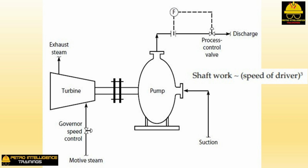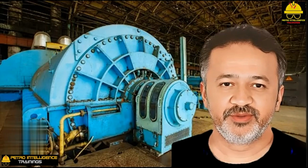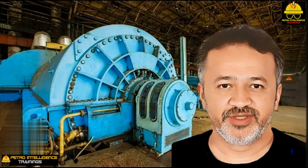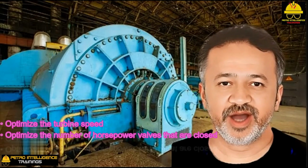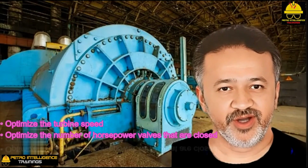Slowing a turbine closes the governor valve. This may now permit us to close an additional horsepower valve without losing our flexibility to control the speed of the turbine. Closing that final horsepower valve will save us another 10% of steam. Our overall objective is to wind up with both the process control valve downstream of the pump and the governor speed control valve in a mostly wide open, but still controllable position. To achieve this dual objective, we have to simultaneously optimize the turbine speed and optimize the number of horsepower valves that are closed. It is rather like solving two equations with two unknowns.